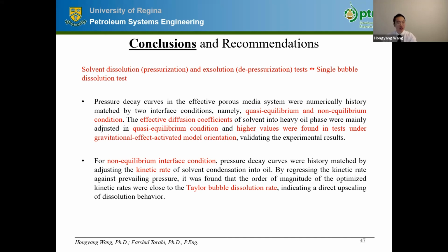And for the non-equilibrium interface condition, the kinetic rate of solvent condensation into oil was tuned to history match the pressure decay curves. And we've also found that the order of magnitude of the optimized kinetic rates was close to the Taylor bubble dissolution rate, which indicates a kind of direct upscaling of dissolution behavior from a micro scale to a lab scale.